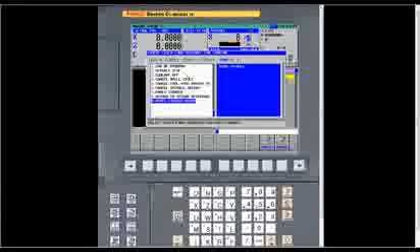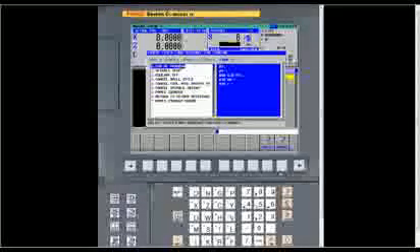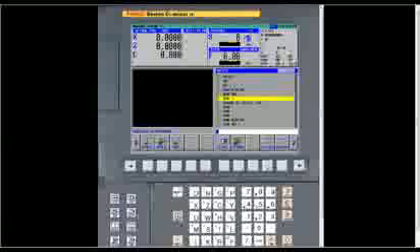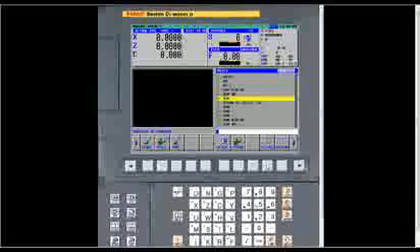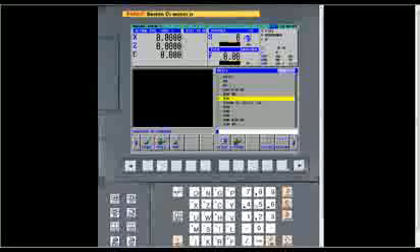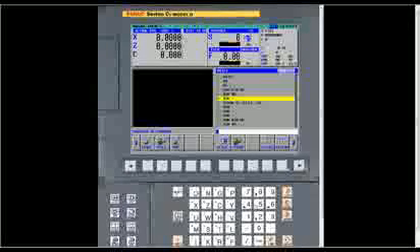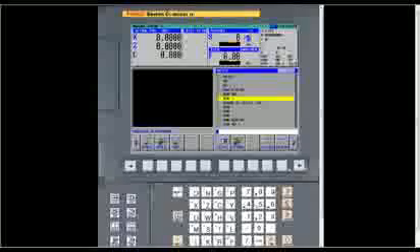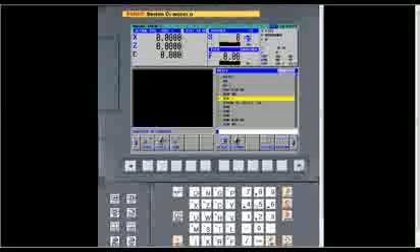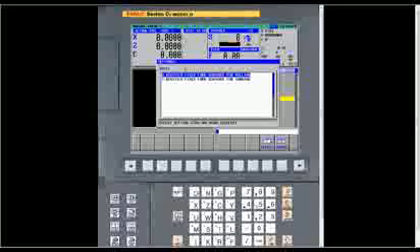I've got a parts counter macro. I can just paste that into any program. And then when you actually want to put that within a program, you just press insert, and it actually adds it to a program. Now, I showed you my fixed forms, and after this is over, if you need to contact me direct, I can help you develop these fixed forms. But then to actually make them yourself, if you go right shift until you see a soft key called settings, you go into that. It takes you into the basics where you can either set them up for milling or turning.